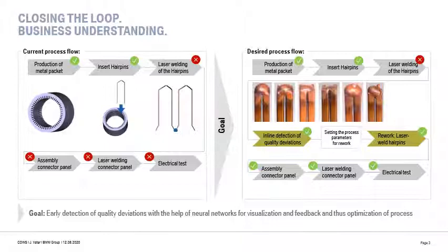As already mentioned in the title of the publication, this paper deals with the manufacturing of the stator of an electric motor. To increase the power density of the electric motor, it is necessary to develop new and innovative technologies for the production and to increase the efficiency of the electric motor. The so-called hairpin technology is a novel technology to increase the efficiency of the motor by replacing traditional copper windings with thick copper bars.